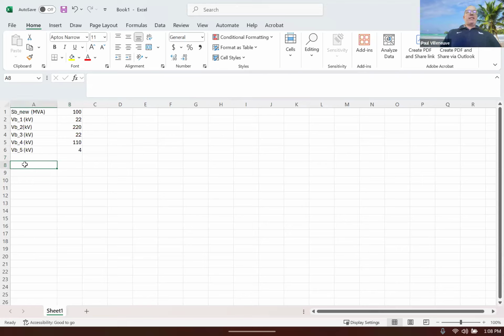Now, if I want to go ahead and convert, yes, sir. VB, yes, for each of the regions that we've specified, wherever there's a transformer winding. Yep. That's the Z base in that region as well. Not how much impedance, that's what the base impedance is in that region. So that's our ratio to set everything up. That's like our base value for how we will ratio the actual impedance of a line or a transformer to that quantity.